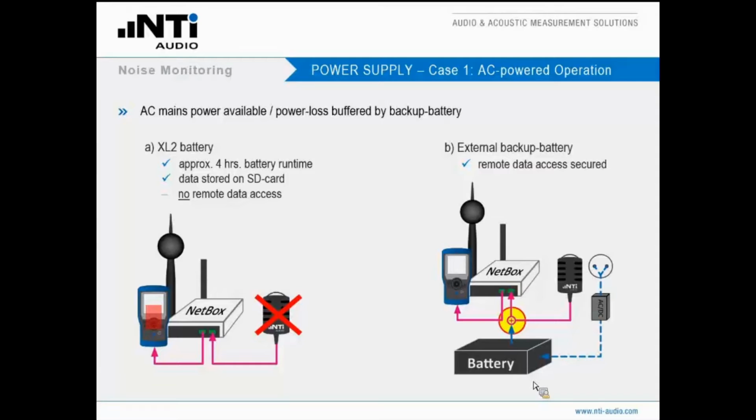So it is important that you make yourself acquainted with the requirements of the battery you have chosen so that it fits the power supply of the noise monitor. Unfortunately, it is not possible to provide a general solution that works for all occasions. You really have to find out what your demands are, then select the battery, and then the appropriate charger.